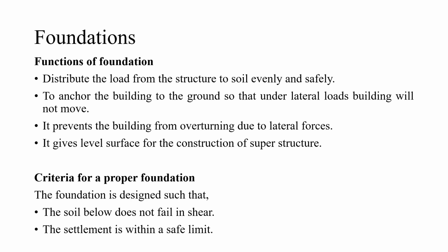What is the criteria for a proper foundation design? There are two major criteria. One is the structure should not fail by shear, and the permissible settlement criteria should be satisfied. That is, the settlement should be within the safe limit. You are constructing a structure over which you are adding the load, and it will also have the self weight. There is some point where the soil cannot withstand any further load and it will fail. That is the shear criteria.